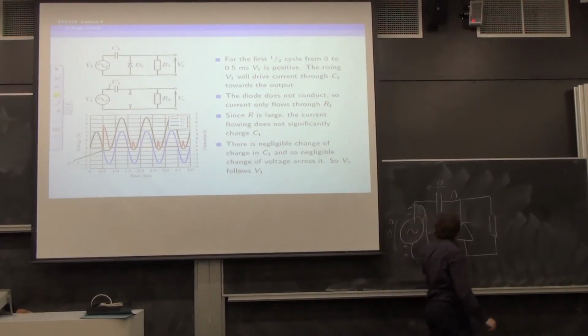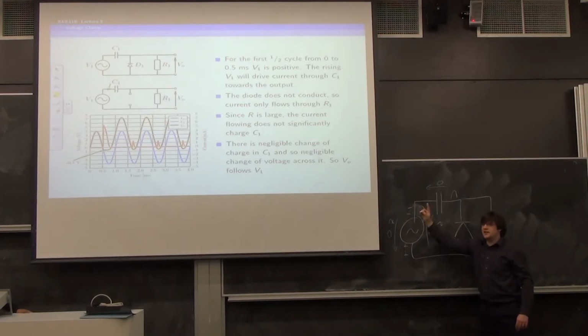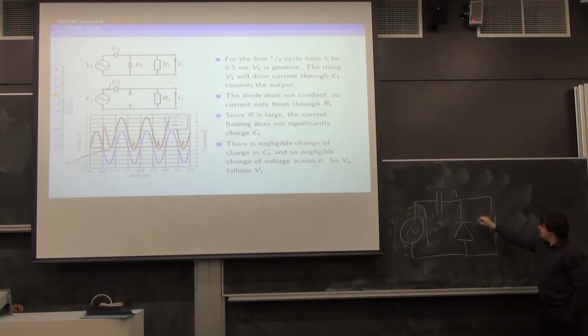In this situation, because this has still got no charge, this should be close to whatever this value is, and I'm calling this value my reference. So I'm saying this is 0.7 volts above this, facing that way, which is the same as this is 0.7 volts below this. It all depends how you like to think about it. Anyway, the upshot of all this, 0.7 this way, that way, is we end up with 0.7 volts across the diode in the direction which will cause it to conduct, which is 0.7 volts on the anode greater than the cathode.